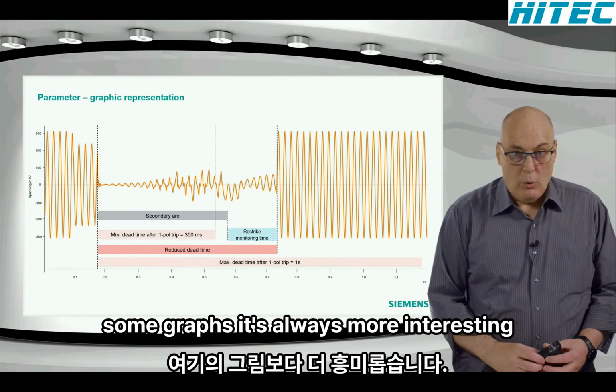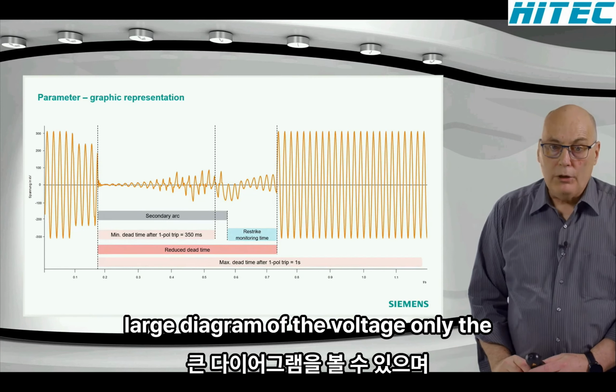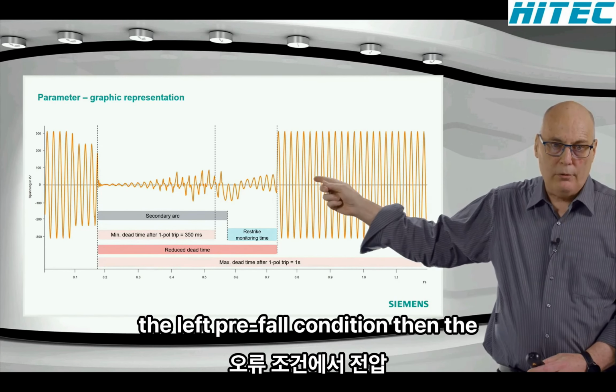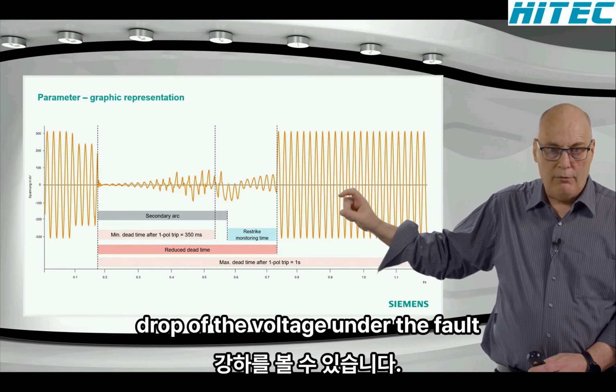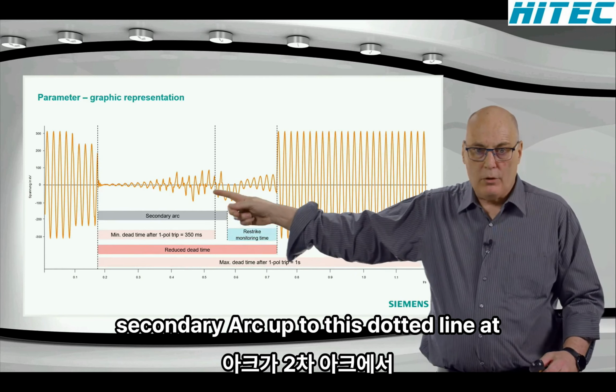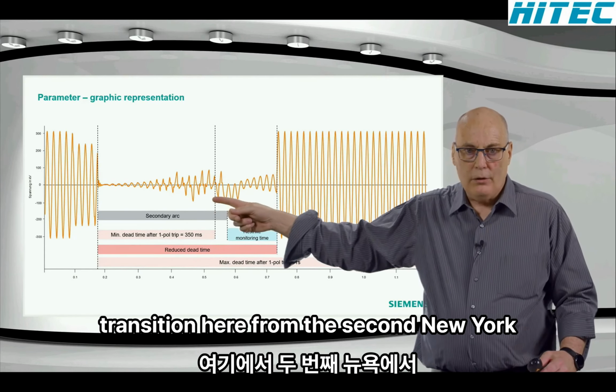Some graphs, this is always more interesting than a picture. Here you can see a nice large diagram of the voltage, only the voltage now. And you can see starting on the left, pre-fault condition, then the drop of the voltage under the fault condition, then the breaker open and the secondary arc up to this dotted line is secondary arc. And you can see the transition here from the secondary arc to this one.